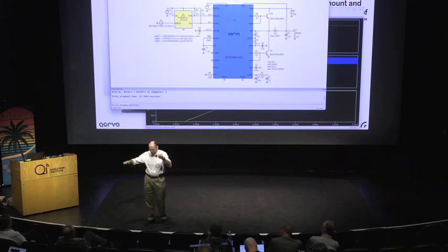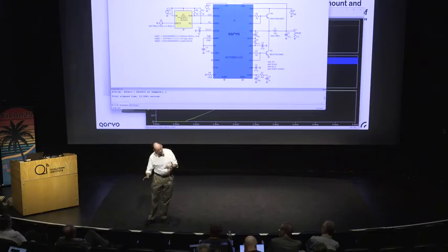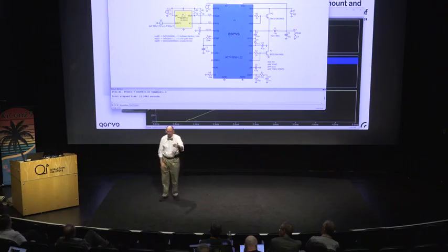Because if you just use a hyperbolic tangent, the capacitance vanishes at high voltages, and you can't solve the circuit. It's not physical. It doesn't work. So you specify the value asymptotically approached, the initial value and any point in there, and then it's going to have the right second derivative through the whole thing. Is it going to match more points? No, but it's probably okay. And same for inductors. Oh, nice. Oh, and it has a transformer.